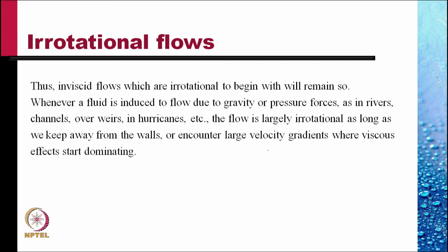Whenever a fluid is induced to flow due to gravity or pressure forces, as in rivers, channels, over weirs, in hurricanes, etc., the flow is largely irrotational as long as we keep away from the wall or encounter large velocity gradients where viscous effects start dominating.